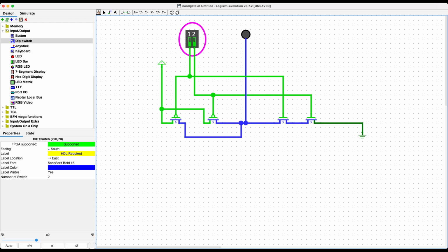Well, we could, or we could be smart and just put together the two things that we've already done. Because if I follow this with a NOT gate, what do I get? I get an AND gate. Okay, so we know how to build a NAND gate. We know how to build a NOT gate. So if we put the two together, could we build an AND gate?